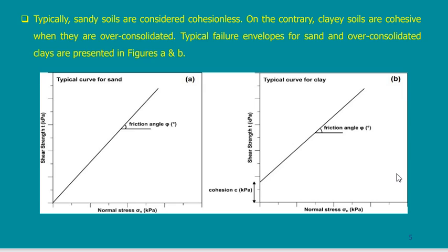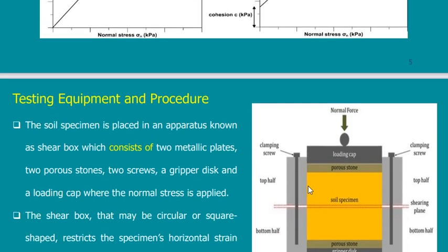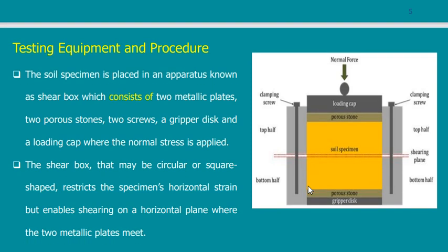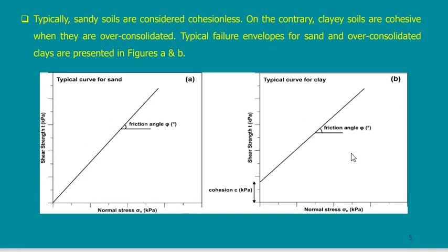Maybe it is a very low phi, but I will have phi. But in sand, if I have pure sand, you are 100% sure that C is equal to 0. But sometimes in clay, though you have C, you may have small angles of phi. But in an exam, if I tell you that you have pure clay and I do not give you the value of phi, then you will take it equal to 0 without discussion.